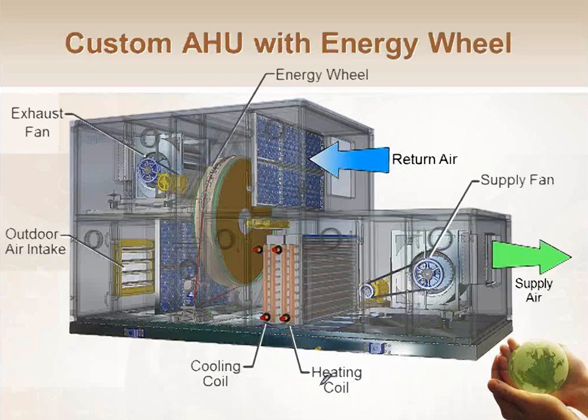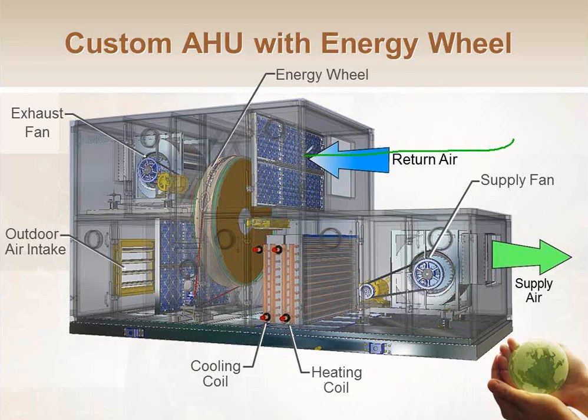All right, so here's a more complex air handler. Actually, not really more complex. It's just a sexier looking drawing, because we can make HVAC pretty sexy here. So here's my return airflow path coming back from the space. It gets filtered, because we always want to filter it before it goes through the wheel, which it goes through, gives up its energy, and then gets exhausted out of the building. So my air molecules follow that path on out. My energy goes this way down the wheel.